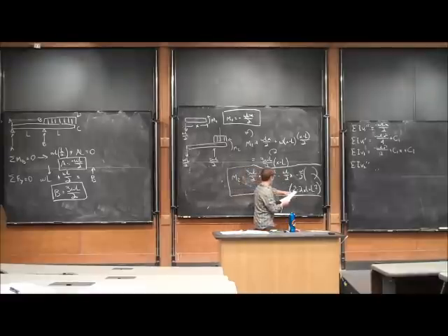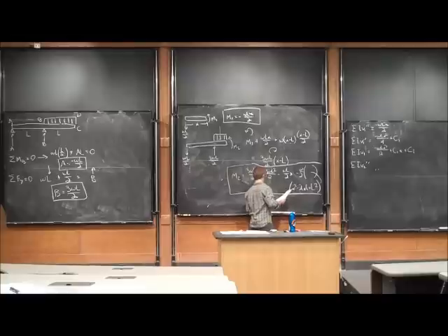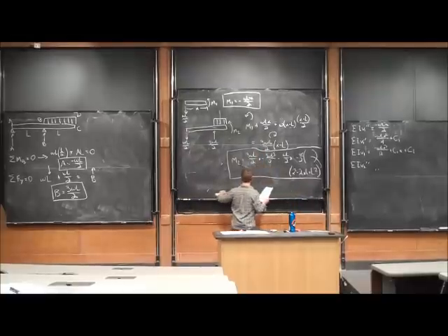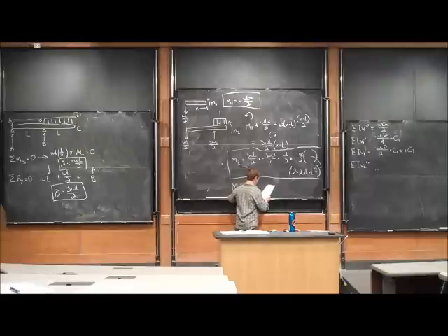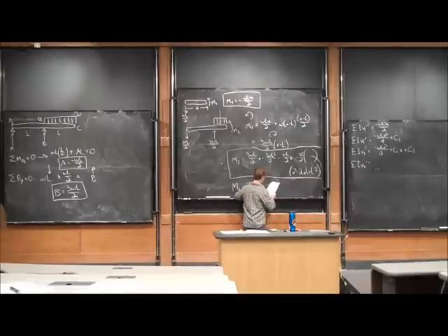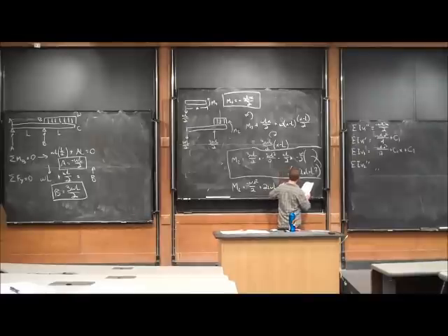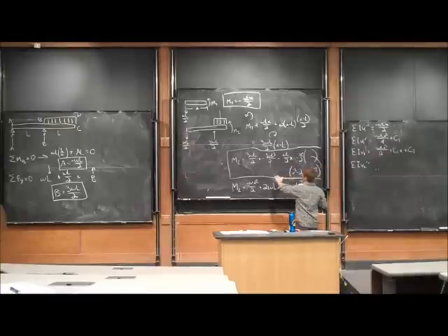If you multiply this out, some of our terms go away, and it actually simplifies even further. So our M2 ends up being negative WX squared over 2 plus 2WLX minus 2WL squared. That's when we multiply this through. It's actually going to clear up some terms here.